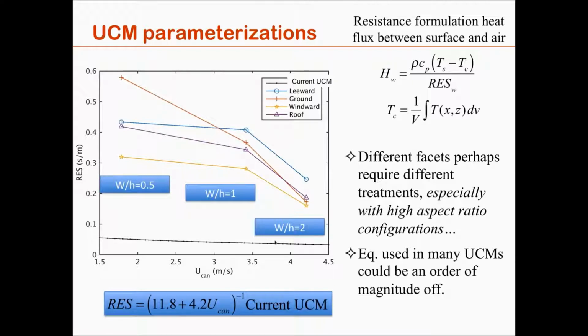But when you have a model with errors that are offsetting each other, something has to give. So if you calibrate it to get you the correct surface temperature, you're not going to get the correct heat flux, and vice versa. So a better way of proceeding is to use improved resistances based on these LES, and then calibrate the model correctly.